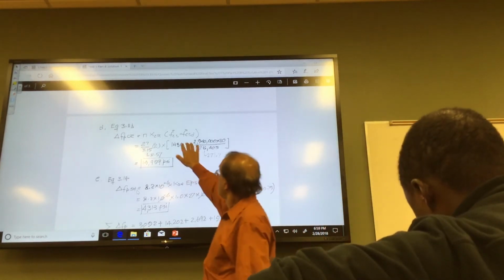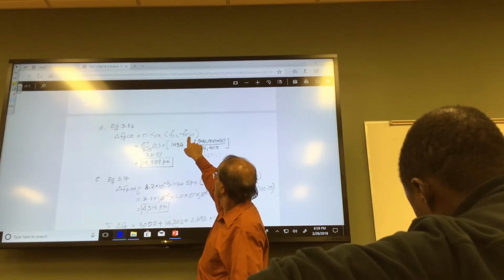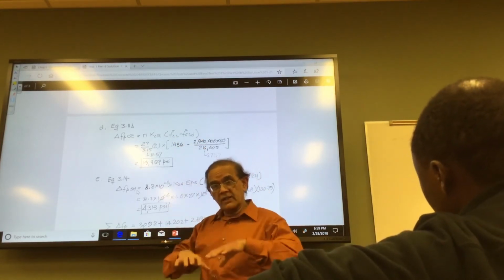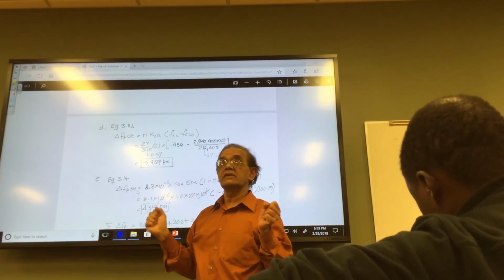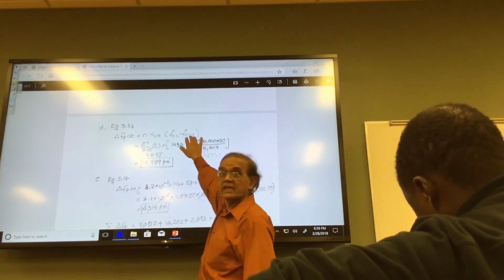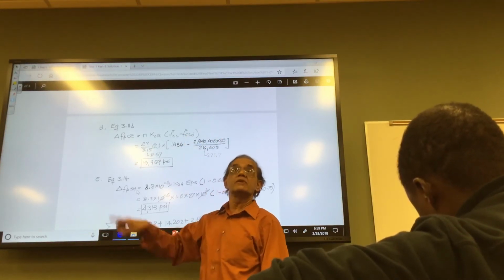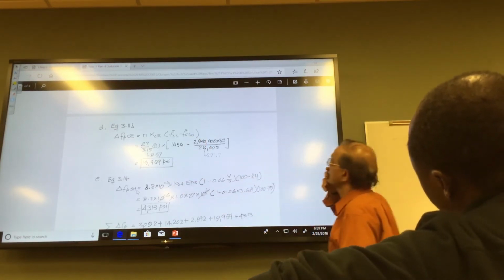At that level, the concrete stress that was without the superimposed dead load is subtracted by this, because as you apply the load, the compression that you had is decreasing, right? So this is how much compression has decreased at the bottom fiber, or the fiber where you're calculating, right? That's why this is subtracted, okay?